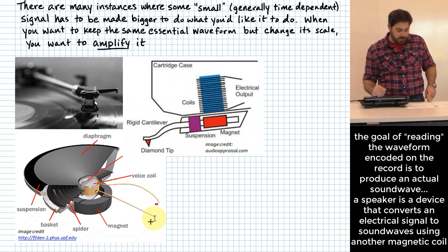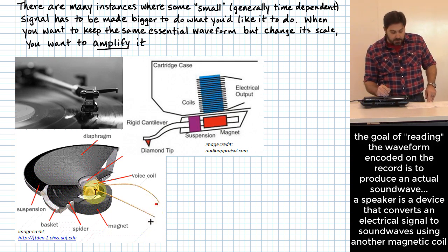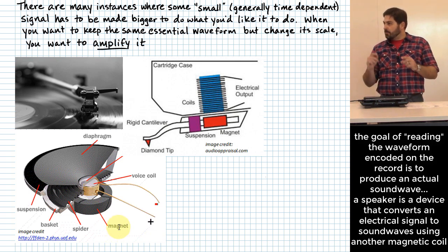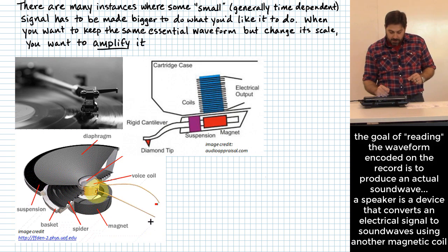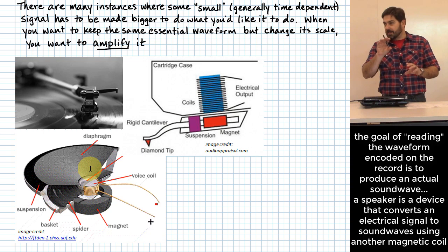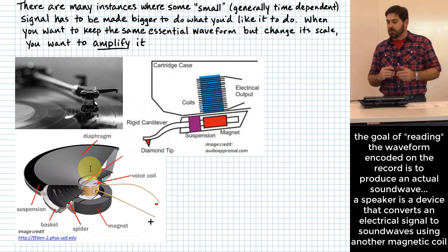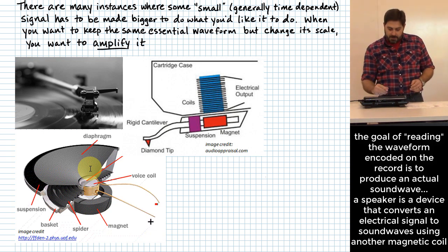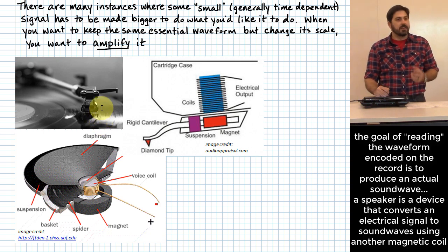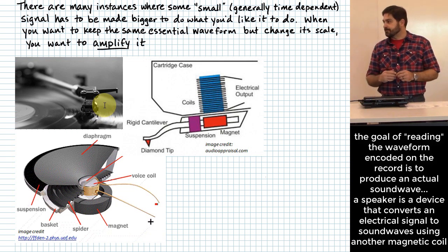And the way that typically works in these stereo systems is that you can drive some kind of voltage across two leads of a speaker, and inside the speaker you have another coil. That coil is positioned relative to a magnet, and by driving current through the coil of the speaker, it causes the speaker to want to move in and out, usually fairly rapidly. And then by moving in and out, it moves air, and then you can hear what that sounded like, okay? So it goes all the way from having little bumps on a vinyl track right here, all the way to the point where it's creating these sound waves that you can then hear, okay?